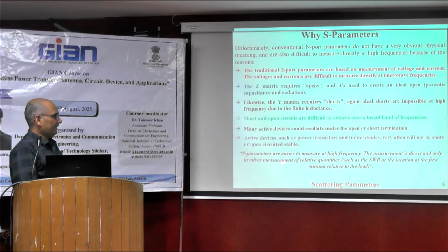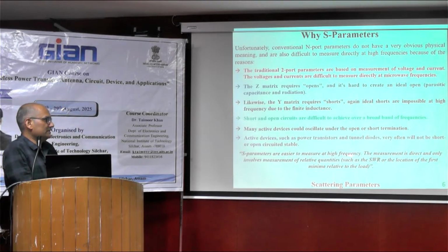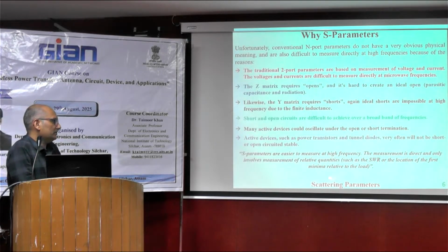S parameters are easier to measure at high frequencies. The measurement is direct and only involves measurement of relative quantities such as standing wave ratio or the location of the first minima related to that load. That is easy as compared to measuring the voltage and current at high frequencies.